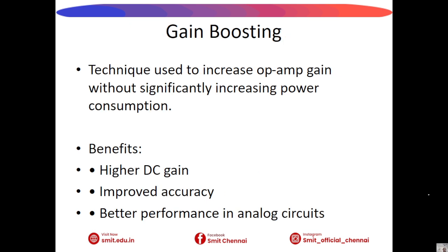Next, we see about the gain boosting. Gain boosting is a technique used to increase the effective gain of an amplifier without significantly increasing power consumption. This is commonly achieved by adding auxiliary amplifying circuits that increase the output resistance of certain transistor stages. Higher gain improves accuracy, precision, and overall amplifier performance, especially in integrated analog circuits.